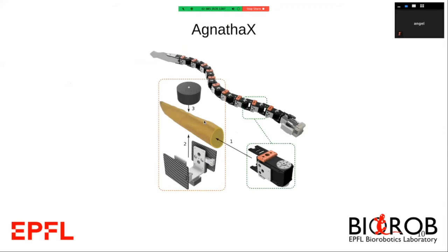And outside, we have this sensory feedback that in this case are load cells, each one on one of the sides. And here we have the circuit. On top, we have some styrofoam because the sensor itself creates some load that makes the robot sink. So in order to compensate for that, we make it float with the styrofoam.